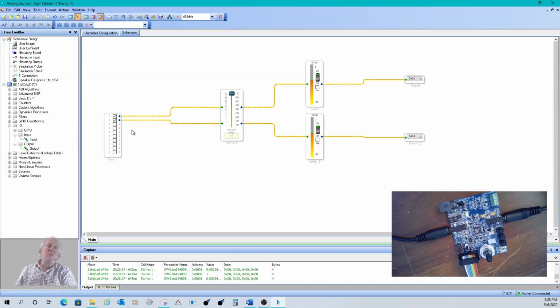They assume you just do it in a DSP. Most codecs will have a high-pass filter setting in the ADC. I recommend you select that in your options. When you're dealing with a codec or an external ADC, turn on the high-pass filter. It's free processing. It's generally a corner frequency of less than 1 hertz or less than 3, so generally it's not a problem for your audio bandwidth.